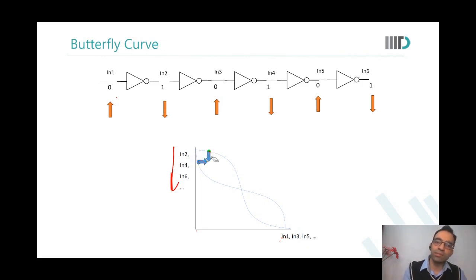Are you able to see this? So it means that my circuit is safe for this amount of noise. If this amount of noise comes, then the 0 I stored on N1 will go to this value, and the 1 I had stored on N2 would go to slightly lower than that. But I will still have 0 and 1. Are you able to see this? Any questions?